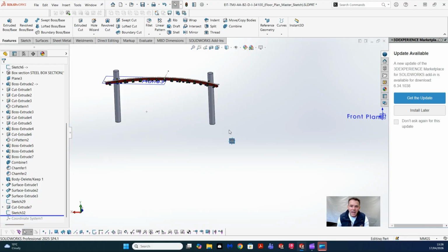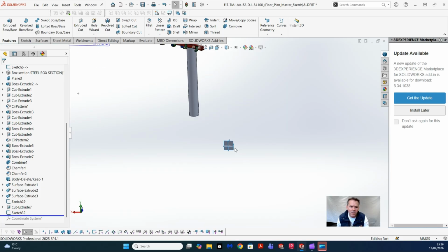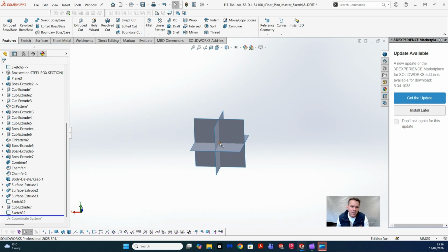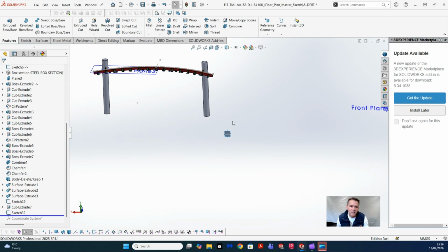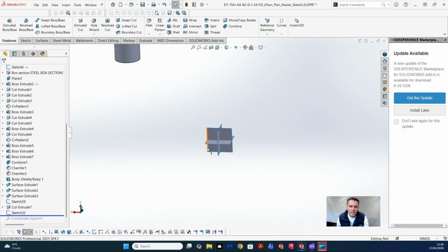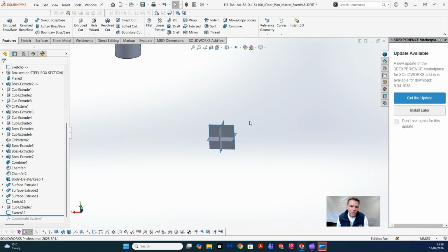In order to prepare this new position, you do need a point. You're going to need to set up a point where your origin is going to be. It could be any point on anything. But because we want this in this position, this is where we want to set up our new origin. I have drawn a sketch on this surface and then created a point that is the intersection of all three surfaces. That just gives us our reference point, but there are various ways in which you could do that.